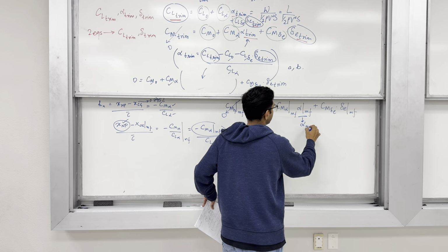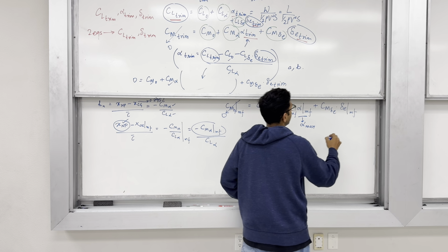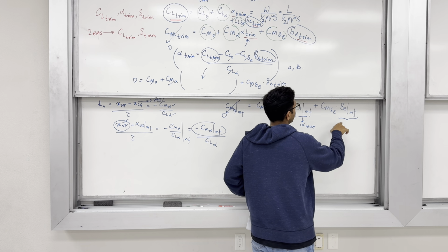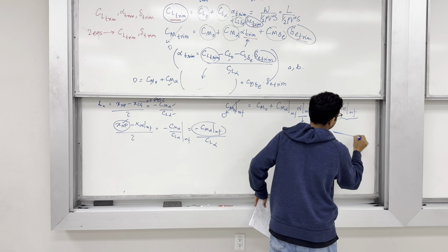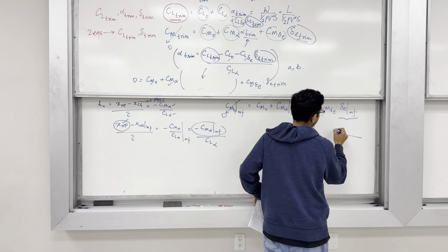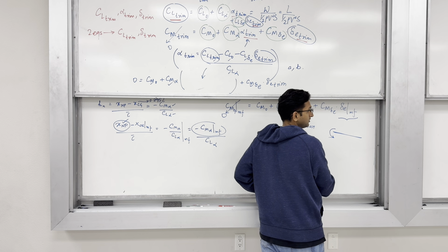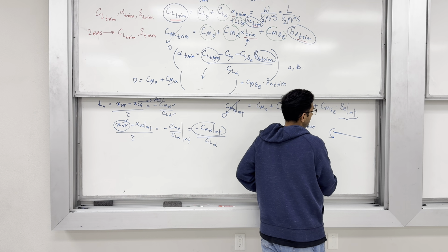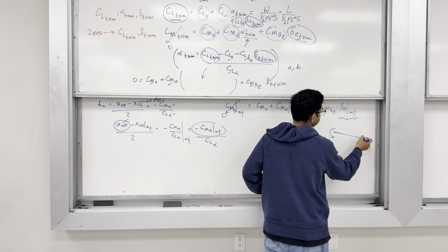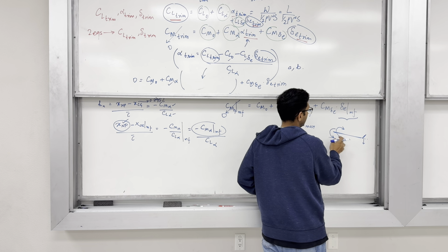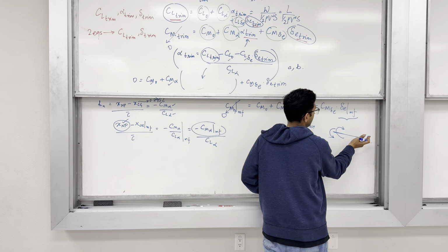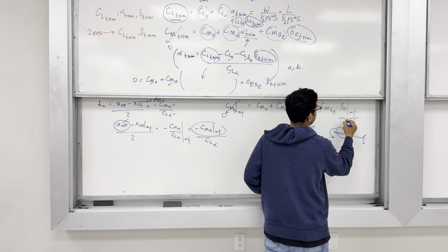So, this is going to be the maximum alpha I can fly at. And if you are confused about the sign of the deflection, just make a small sketch. I know that at landing most of my pitching moment contributions are negative, which means that I have to make my deflection this way, so that a force can act which gives me a positive pitching moment and cancel out the negative pitching moment.